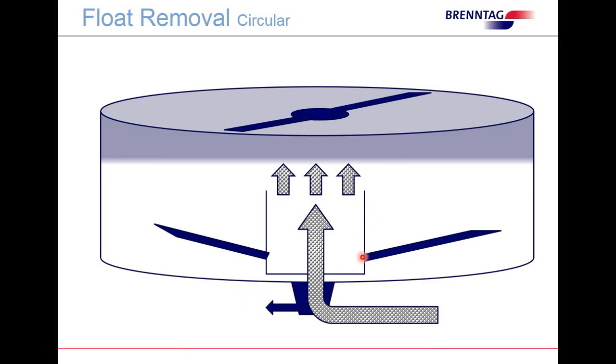I do want to talk a little bit about a story at a meat packer I went to, and we were having major problems with carryover out of the DAF unit. No matter what we did, we couldn't control it. Running numerous tests, adding different locations of the polymer and recycle and things along this line, and really had no success whatsoever. And I happened to go to the plant early one day. I was not supposed to be there till later that afternoon, but I came in the plant and the DAF had been drained. And I looked, and somebody had welded a hood over top of the center pipe coming in.